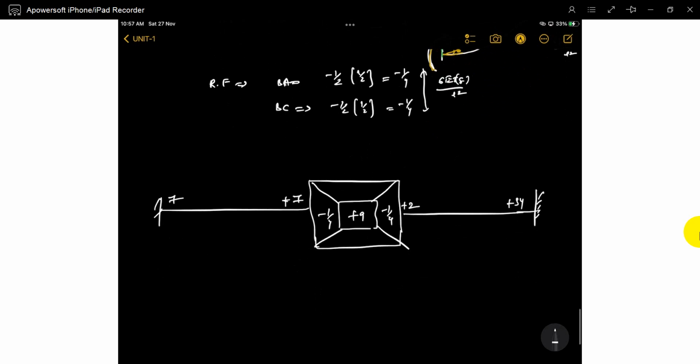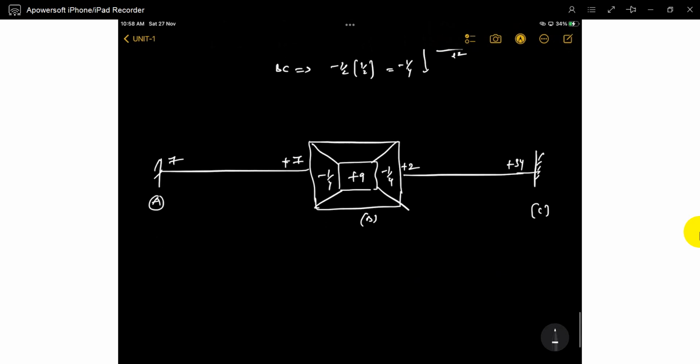Directly just one, because the rotation contribution from A and the rotation contribution from C is 0, because both are fixed end joints. So no need to do anything, just one iteration, one value. For BA, the rotation factor, the sum of the fixed end moments from A and C is 0.